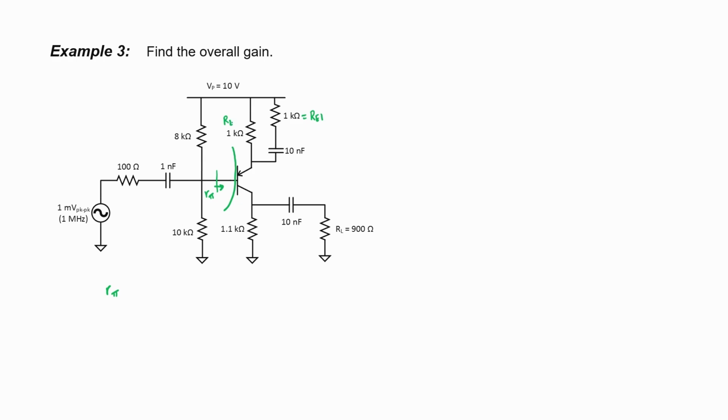Let's find an expression for it, and I'll call this RE right here. Our emitter resistance here, I'll also label little re. Our r pi is then beta times RE, which is in series with these two resistors in parallel. If RE1 is too low, then it starts to make r pi lower and lower, which starts to affect our input impedance looking into the transistor.